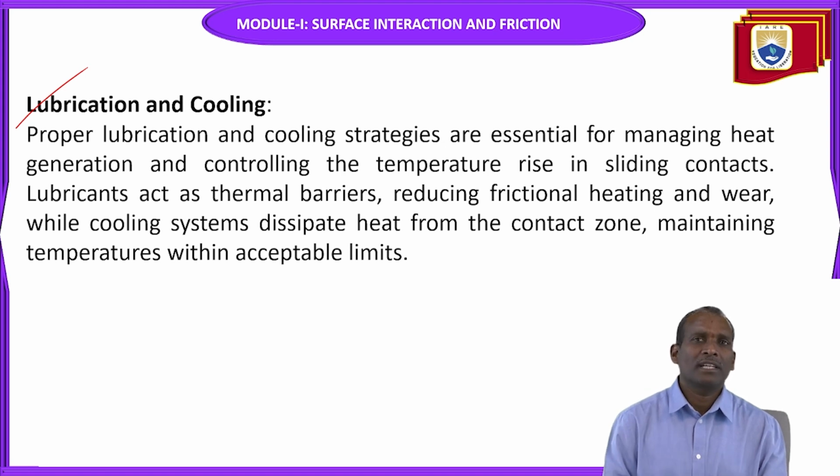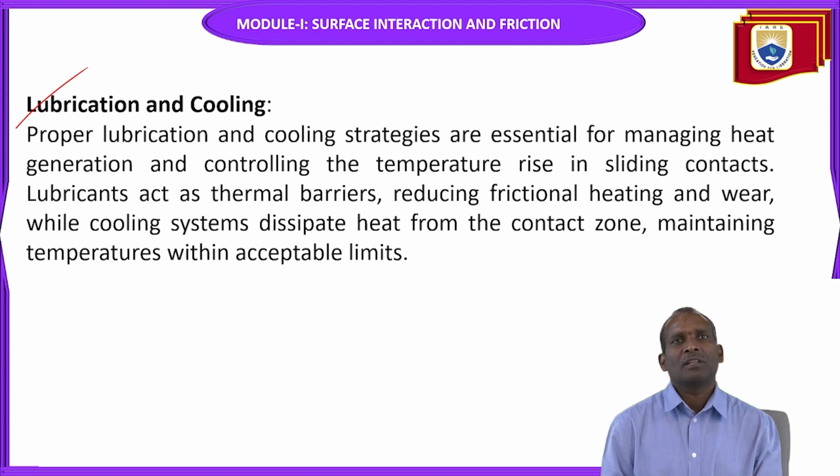How much heat is generated and how much heat is dissipated, that you can also calculate. Based on this calculation of heat dissipation, you can say whether the system requires cooling or not, so that you can maintain the temperatures within the acceptable limits.